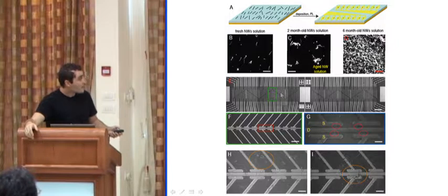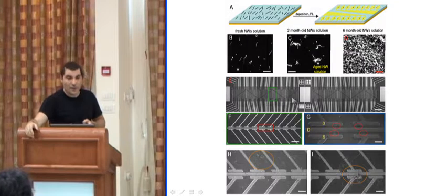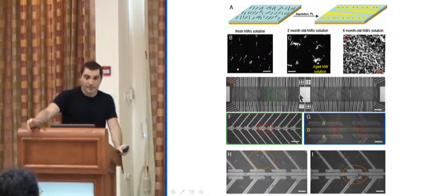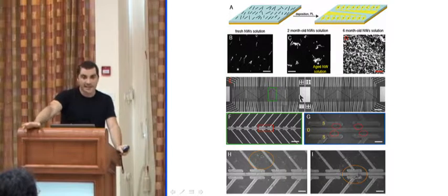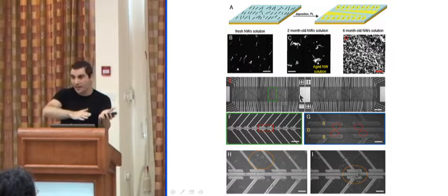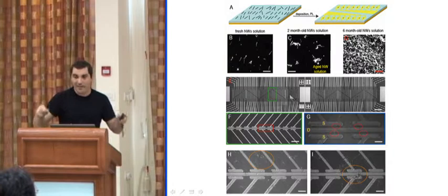So if I have time at the end, we are developing in our lab a new technique that we call new dry transfer techniques, where we actually do not deposit the nanowire from solutions, but we grow the nanowires at certain densities, at a certain alignment from the beginning on the growth surfaces, and then we make a printing process, and we transfer them directly inside windows that we create by photolithography, and we know that just inside those windows we will have nanowires.